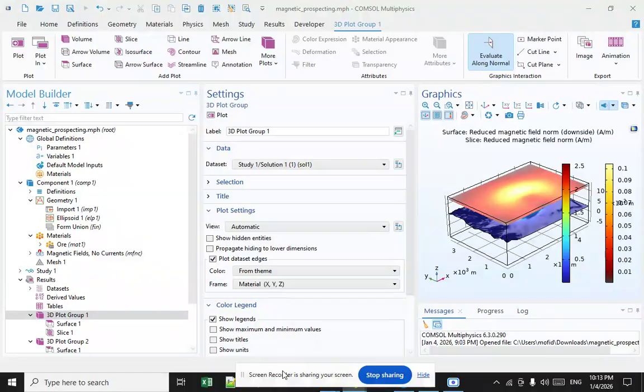Generally, most magnetite banded iron formation deposits must be ground to between 32 and 45 micrometers, which is equal to 0.0013 and 0.0018 inch, to produce a low silicon magnetite concentrate. Magnetite concentrate grades are generally more than 70% iron by weight and usually are low in phosphorus, aluminum, titanium, and silica and demand a premium price.